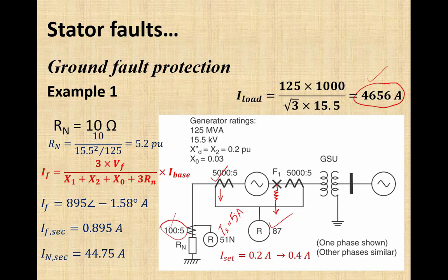What about the motors? Remember, small motors are operated in ungrounded condition, meaning their neutral will be in floating condition, but large size motors may have their neutral connected to ground through a high impedance to limit the fault current to a safe value. So here we have two examples. Maybe we discuss those two examples in any next lecture if we get some time. So we will discuss then how to provide protection to motors against ground fault.